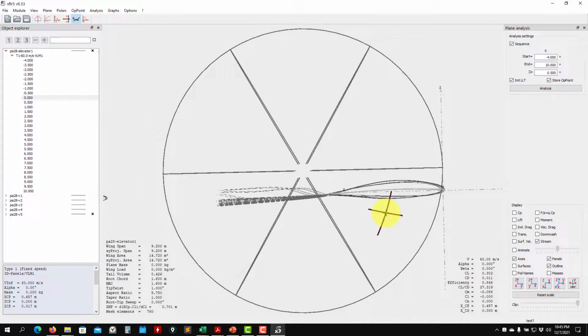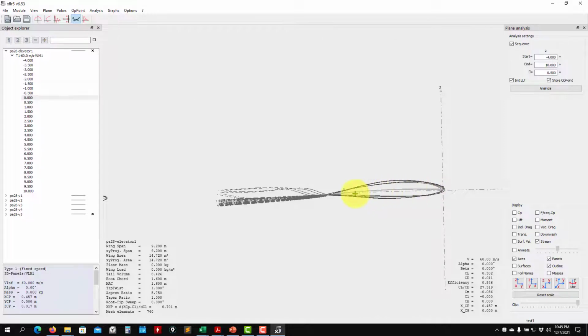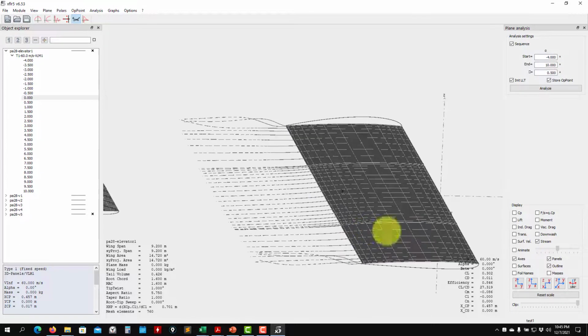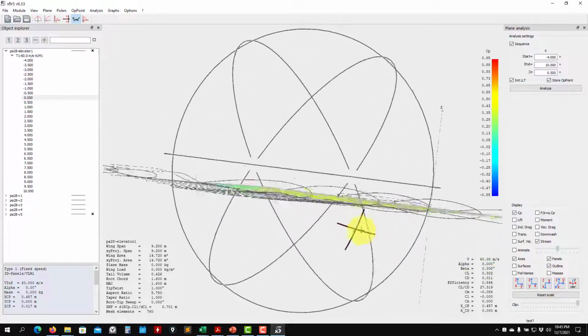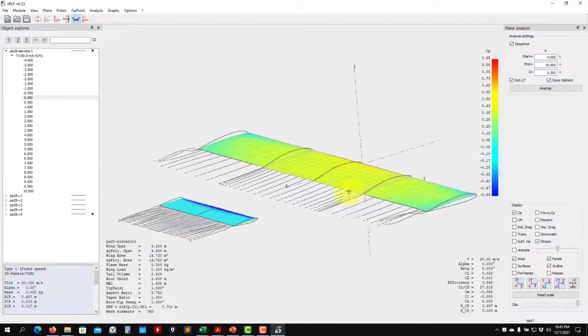It is a surface that captures the curvature of the wing. It is a huge simplification, but it works. We're only interested in resolving the curvature and getting the pressure difference. In the vortex lattice, you get the distribution over the whole surface.